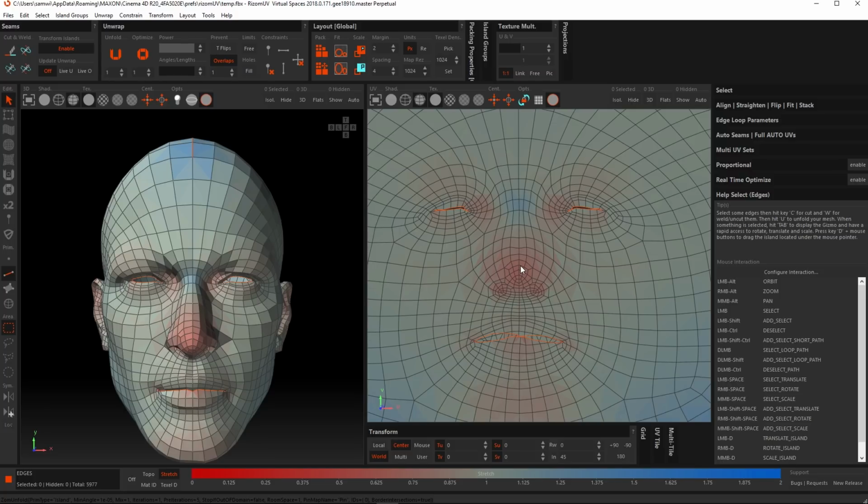There is a good reason for this. The overlaps function only deals with the outer border or extremities of an island. To deal with overlapping UVs on borders in an island's interior, we need to do something else. Let's disable the overlap button and enable the Fill Holes button. Then we'll perform an unwrap again.